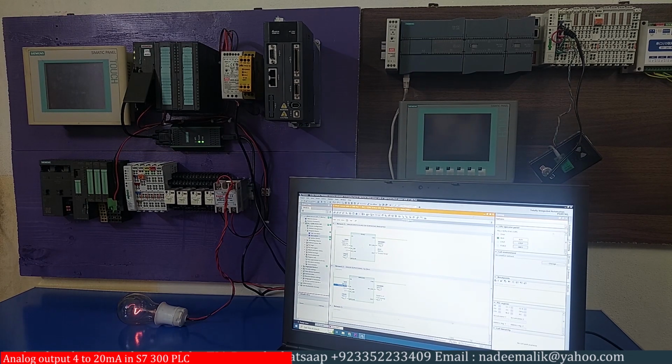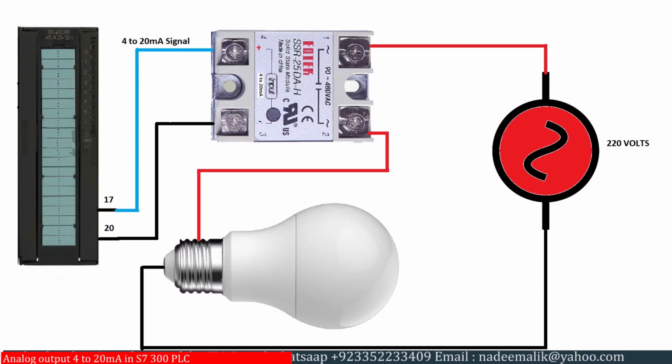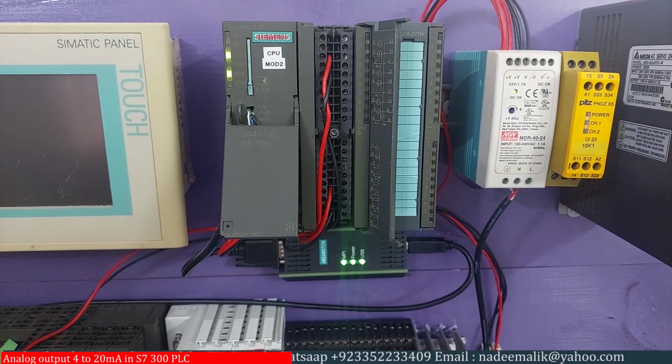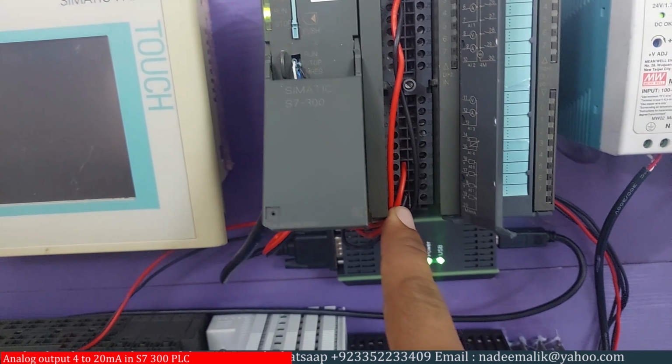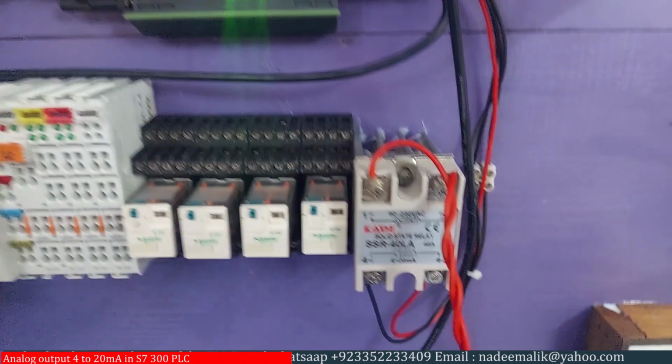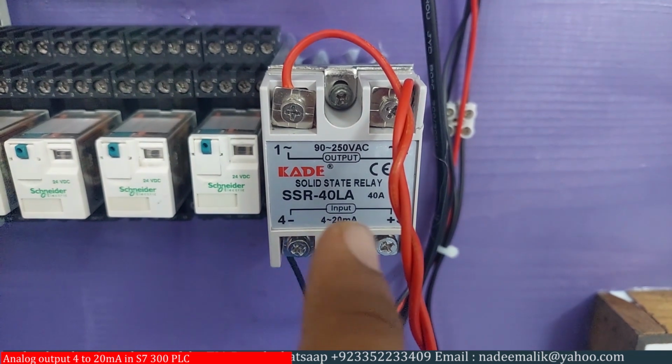Welcome to another training session. In today's session, we will learn how we can generate analog output signals with the PLC. First of all, let's see the wiring for today's setup. We have connected wires from the 4 to 20 milliamp output channel of the PLC to the 4 to 20 analog input terminals of the SSR.